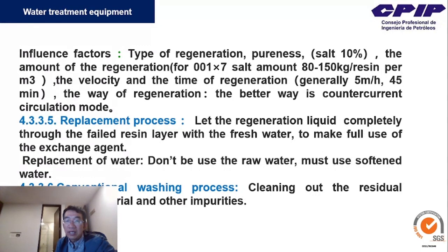The better way is countercurrent circulation model, and the replacement process lets the regeneration liquid completely through the filled resin layer with fresh water to make full use of the exchange agent.